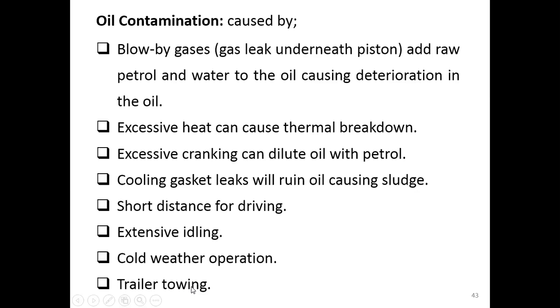And then we have the force feed system, where we use the pump. We start to use the pump, right? So we have the gallery, or the internal piping for the oil, to do the lubrication for the main bearing at the crankshaft, the bearing at the camshaft, and the bearing at the connecting rod. Okay, this is the force feed system. And then we have the combined system between the splash and the force feed system, to help do the lubrication so that the lubrication process can be more effective. And this is almost the last one.